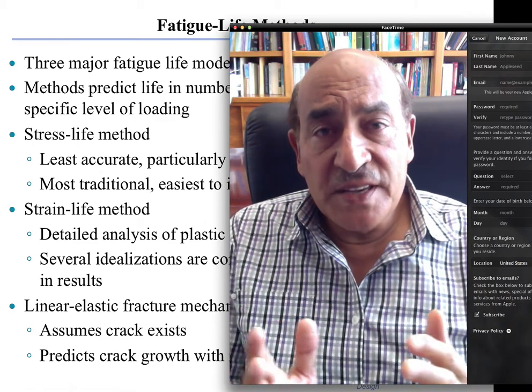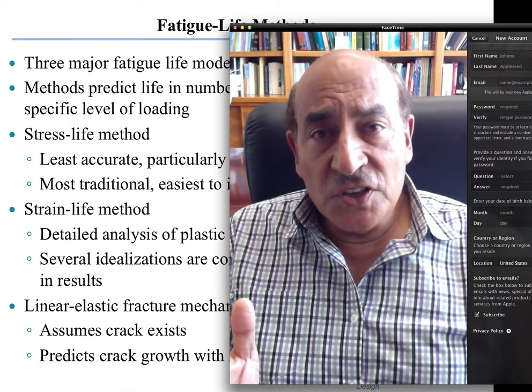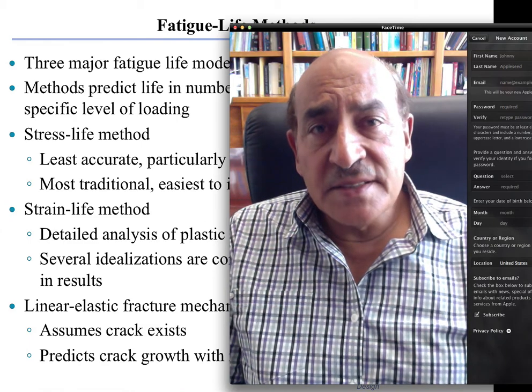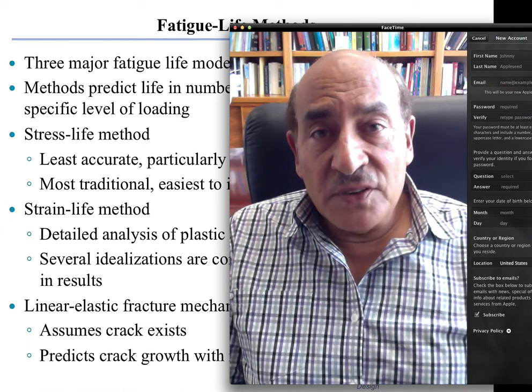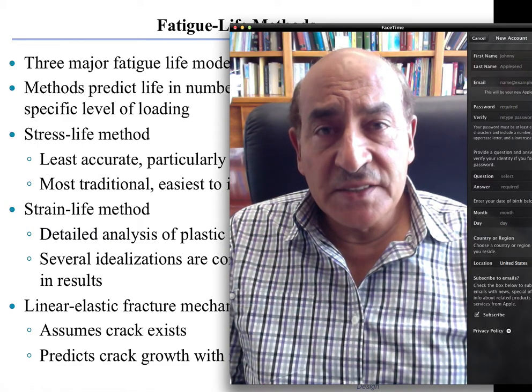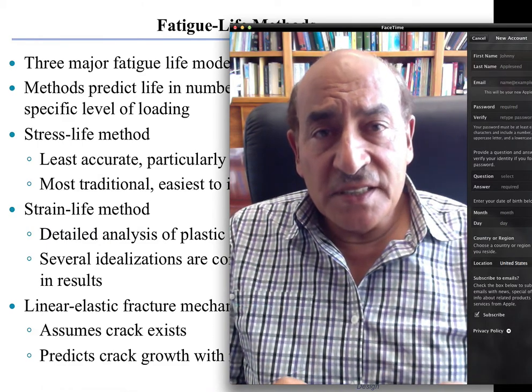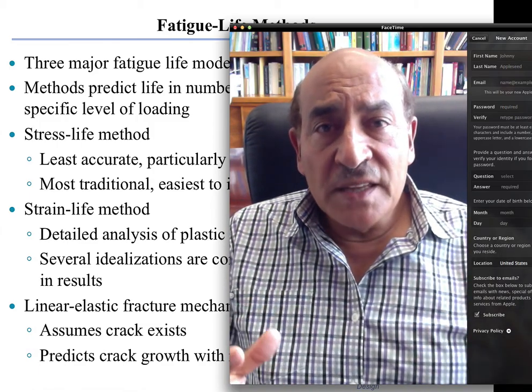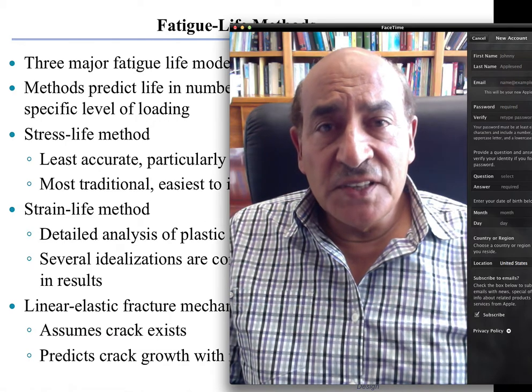So the nucleation phase is very difficult to determine, but assuming that inspection gave us a crack size that has been there for a very long time, but it just suddenly appeared, and we have inspected it and we determine its initial size, then we will follow the crack, and the crack will propagate until you reach a limit.